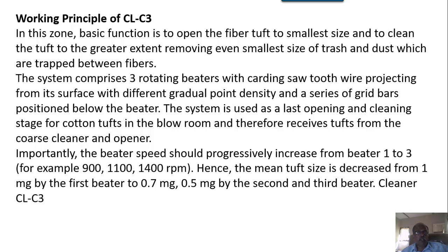What kind of treatment you require, whether you require a high C factor or M factor in the case of a Trützschler line, or you require a relative amount of waste versus cleaning intensity in the case of a Rieter Varioset, that is to be seen. And accordingly the machines are designed.